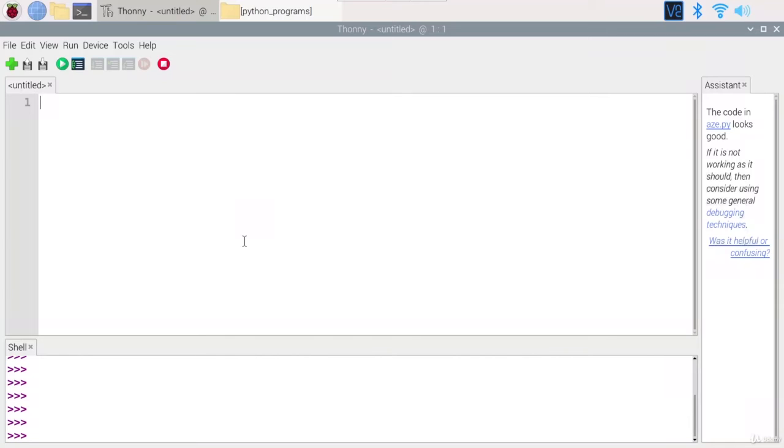Now that the hardware setup for the push button is finished, let's see how we can actually get some value from this button to know if the button is pressed or not pressed inside the Python code. So first of all, I'm going to do import RPi.GPIO as GPIO, okay, as usual. We are also going to import the time module because we're going to need it.